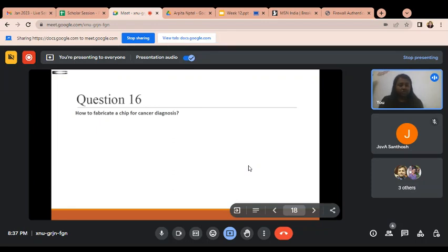So in that case we have to fabricate a micro heater on that. So first we can deposit the nichrome, and we go through the photolithography step, and using this photolithography step this micro heater is fabricated.